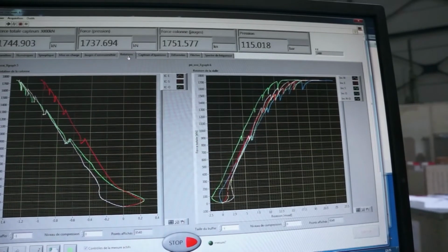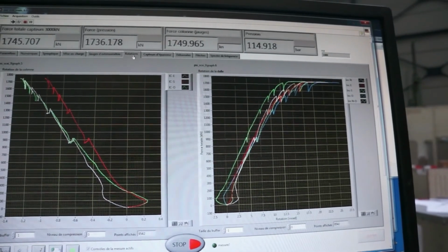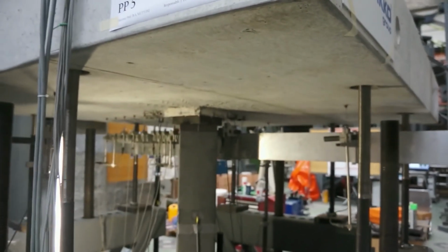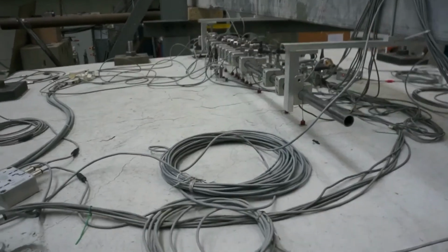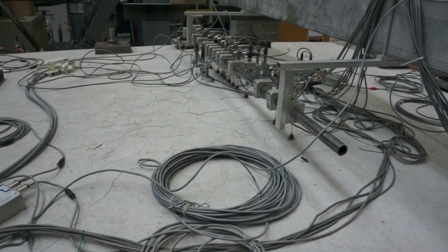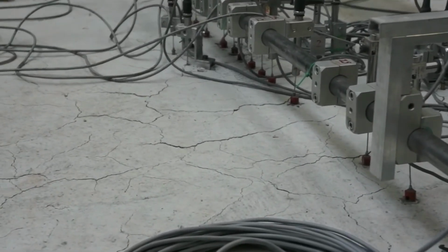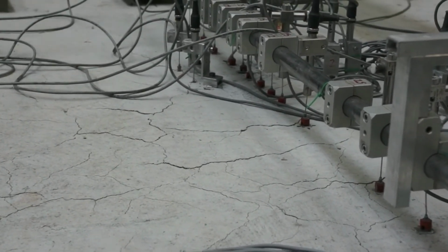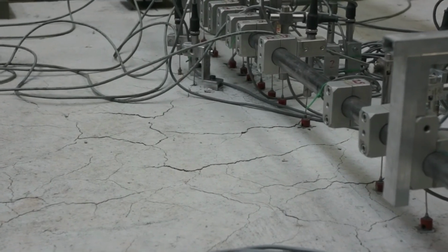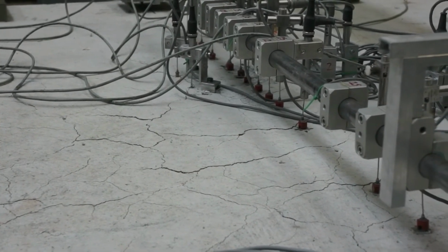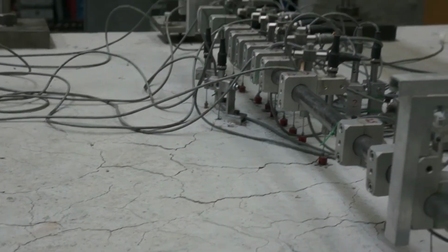Now that's what the curve looks like. We are already at the plateau. The load cannot increase anymore. The deformations are increasing. That means in a real slab, and you can see the cracks on top of this slab, it would tell people that there is serious trouble with the slab. And you can also hear the noises when the concrete is falling down. But at the same time, it still holds the load.